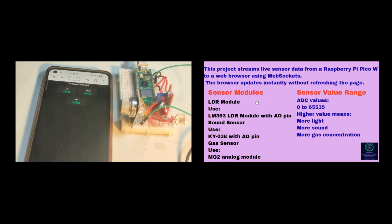Okay, the sensor modules. We have used here an LDR module. This is my LDR module. I have just used a simple LDR module with the resistor; you can use it in module form also. Then you have a sound module, this is my sound module, and there is a gas sensor. All of them are giving some values, which you can see here on my WebSocket dashboard. It is also like an HTTP dashboard, but with WebSocket. So using Raspberry Pi Pico W, we have made this project in MicroPython.